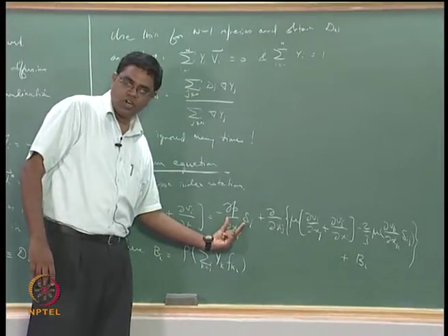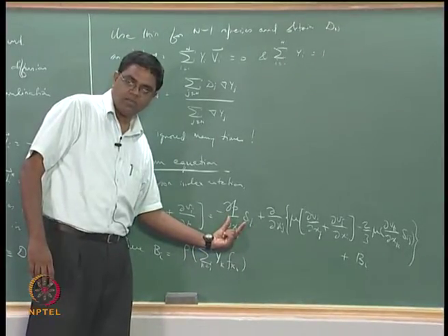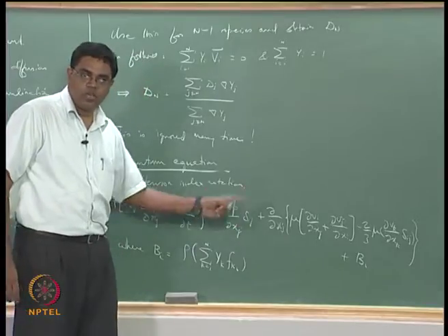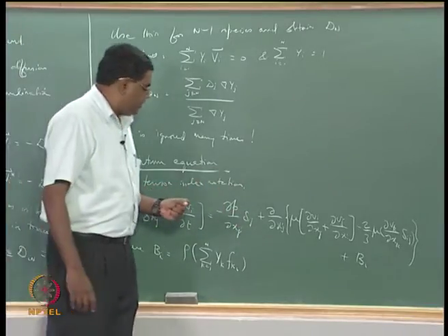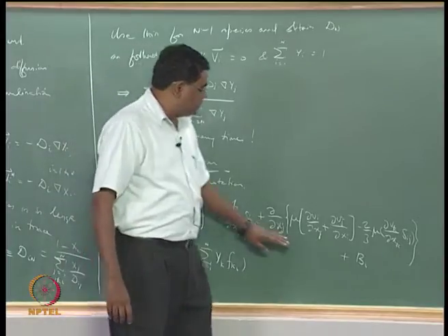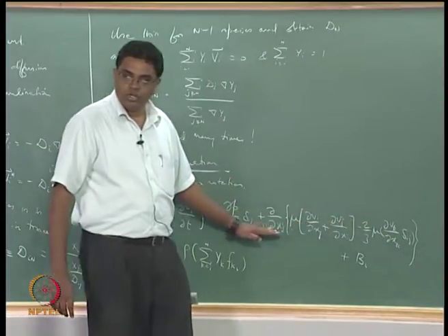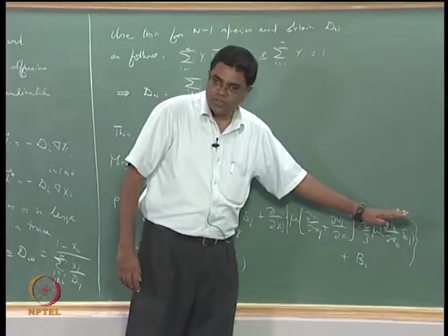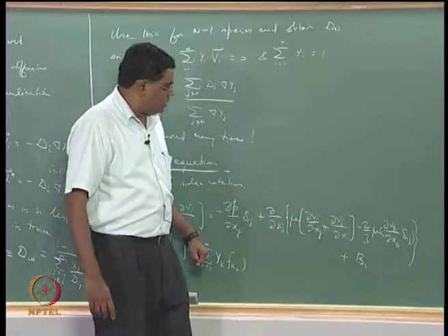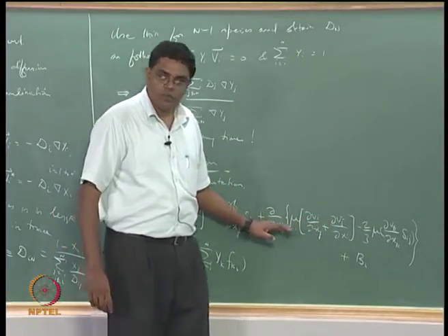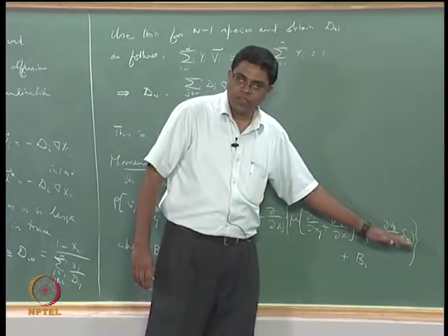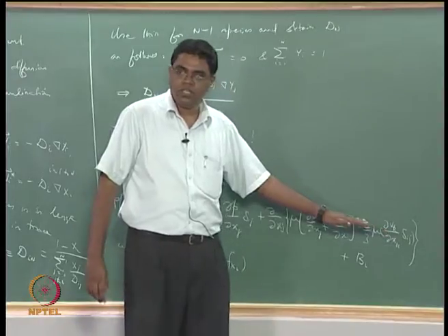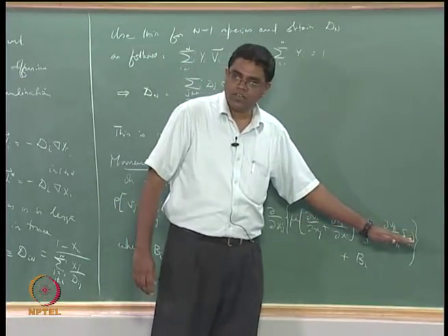So what we used to write in vector notation as grad p needs to go through a complicated route over here. This is first of all assuming that we are looking at a Newtonian fluid for the mixture, or rather we should say Stokesian fluid, because it also has in place the Stokes hypothesis about the relationship between the linear viscosity and the bulk viscosity.